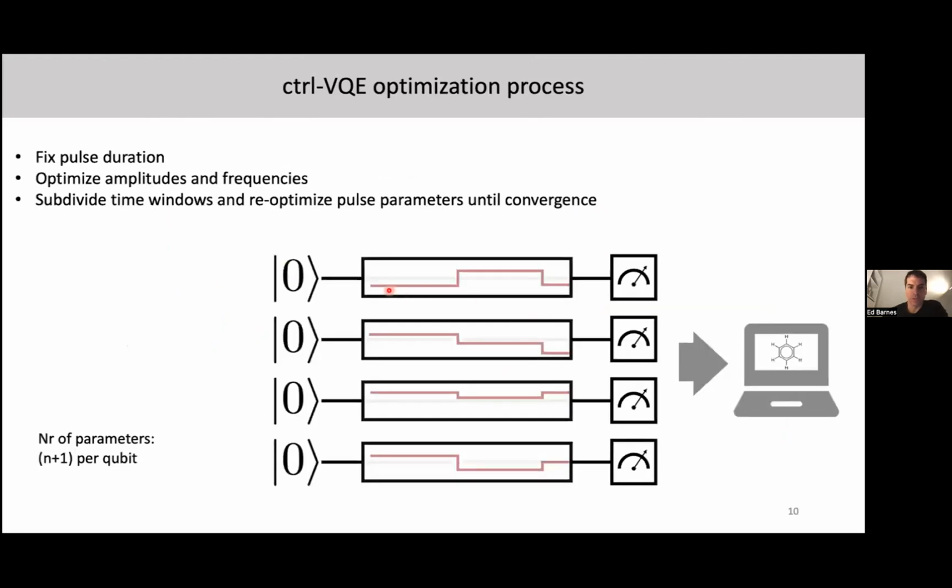So we're talking about something like this, where we have a simple square waveform that transitions to a different amplitude twice. And I would expect that if you impose some rise time limits or bandwidth constraints, this would become just a smoothened step where the rise time could be a nanosecond, within typical AWG limitations. And I would expect very similar performance.